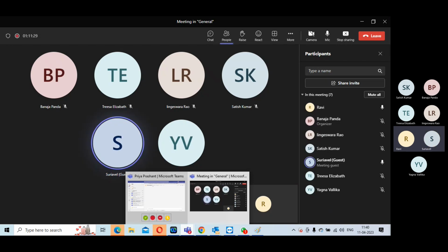If it's not routing, no matter what your timing, it won't close. But the biggest challenges are the timing ones. Irrespective, while everybody will focus on timing, your focus should be: yes, I will cover timing, but unless my routing gets solved, nothing else is important for me. My congestion should be in good shape.